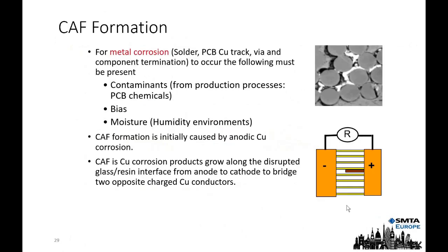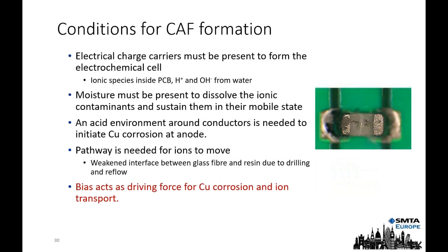If you are interested in this particular subject, certainly Martin will be providing or giving you access to some of the reports that have actually been produced over the last few years by NPL on the CAF formation and the actual failure mode of CAF within a printed circuit board. Now, the condensation test I've mentioned, and I've had a little bit of experience of using this test